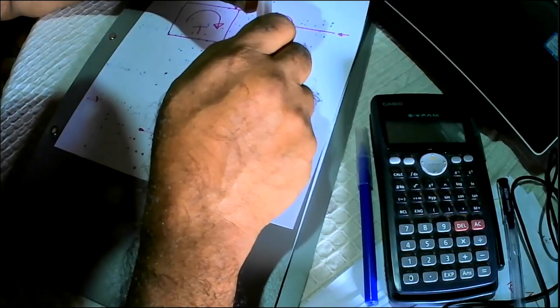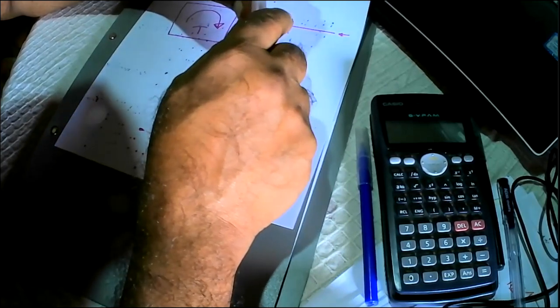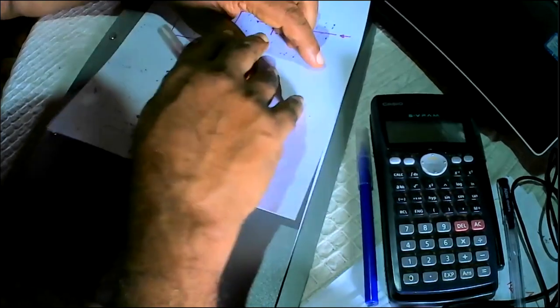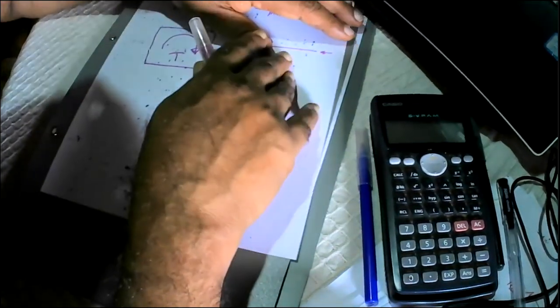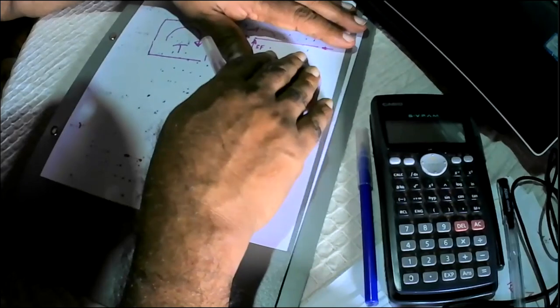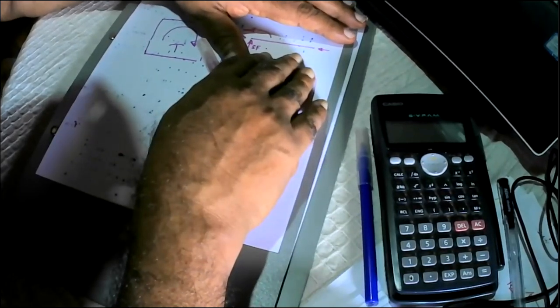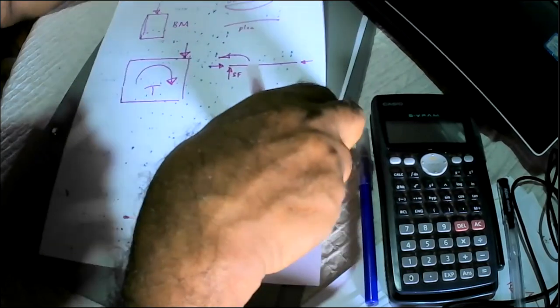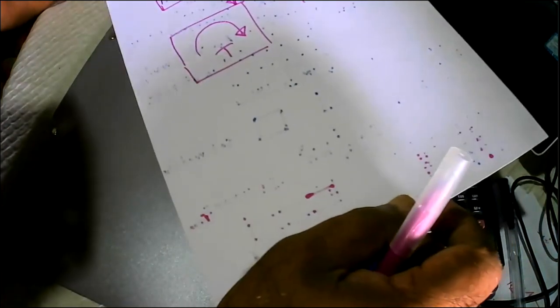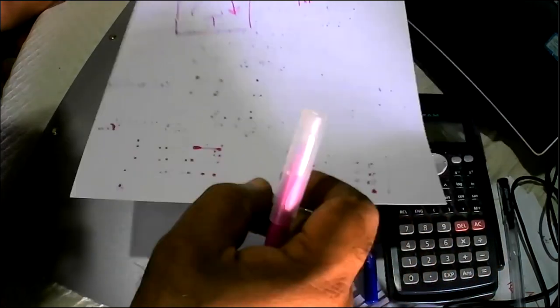And actually what we do is we say the slab behaves like a rigid diaphragm, and there's no deformation of the slab in its own plane. Which means the deformation of all the members in the building will take place like this. That means when the building is rotating, the whole building will rotate by the same amount.